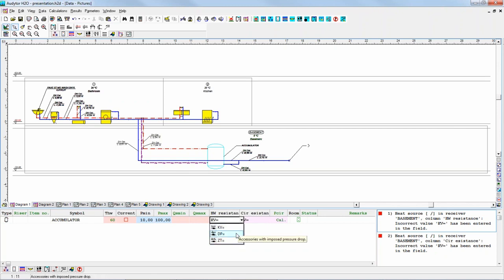The pressure drop in pascals may be the most precise if we know it, but of course we can establish that precisely later on if we have the flow, because of course the resistance depends strongly on the flow. More general solution is to enter the kV factor if we know it for the specific appliance. Let's write 6. Just as an example, I would write both kV 6.